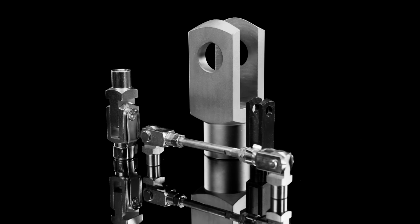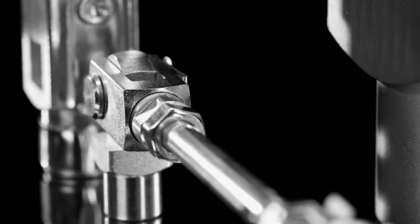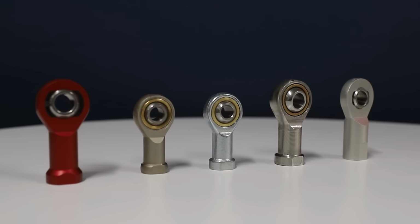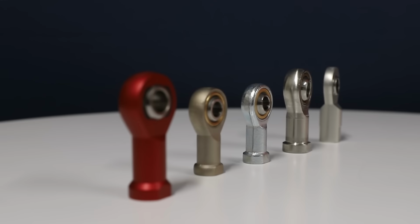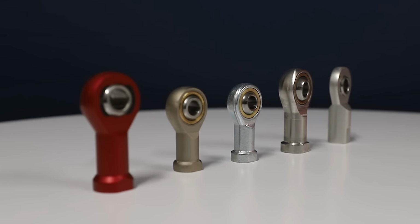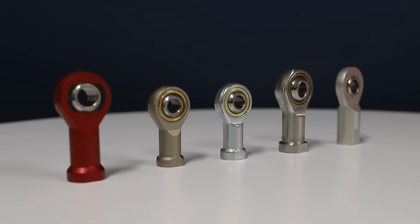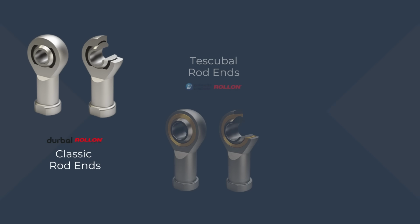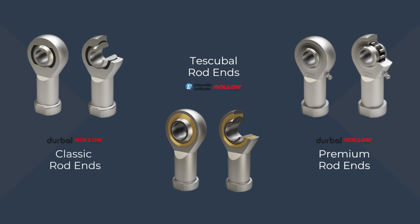So, for example, a rod end with a stainless steel housing and a low friction raceway may not be a great option for an application with very high load conditions. Right. For a high load, we'd recommend a heavy-duty rod end. We'd still use a spherical plain bearing or a straight bearing, but the bearing material would be something stronger, like steel or bronze. We've got various options available for this in our classic, Tescoball, and premium lines.